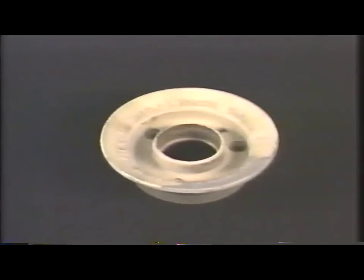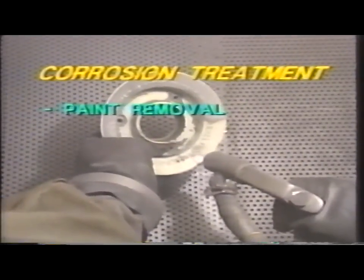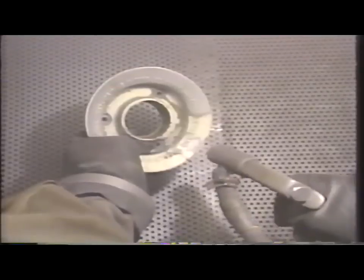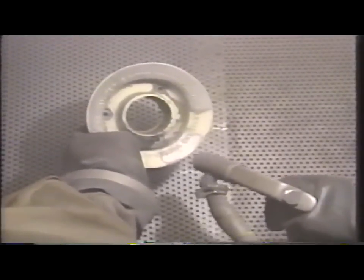If you found traces of corrosion on a painted surface, you first have to remove all the paint in and around the corroded area to get to the corrosion. Paint removal from small areas is usually accomplished by mechanical abrasion or hand sanding. Chemical paint strippers are used on larger areas and should be handled with caution.